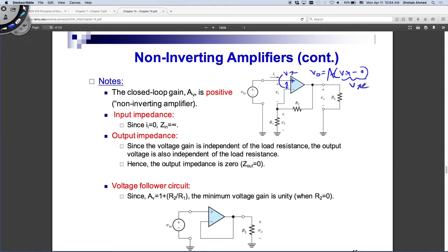Again, we saw that if our op-amp output is going to be influenced by its open loop gain, we just have a comparator, right? That will saturate high or saturate low, because this A is huge. It's the open loop gain. So it's useless, it's only useful as a comparator. So we decided we want to do feedback.